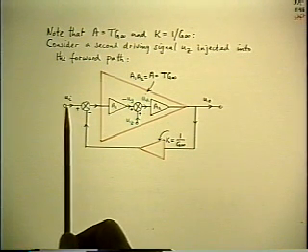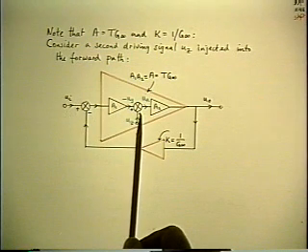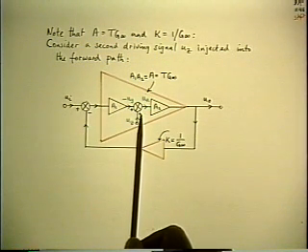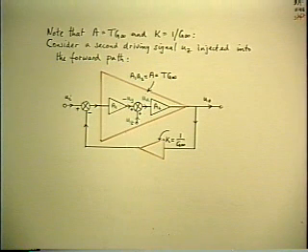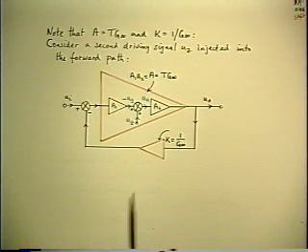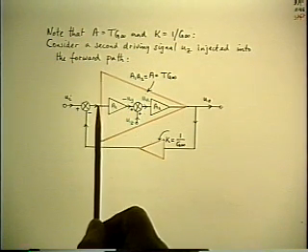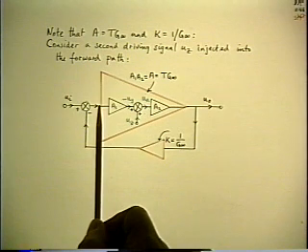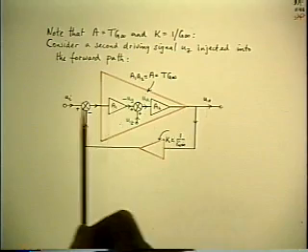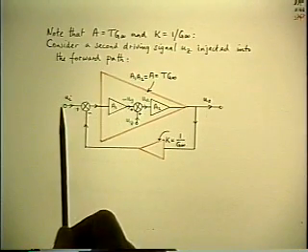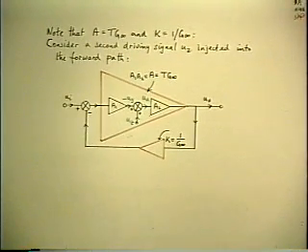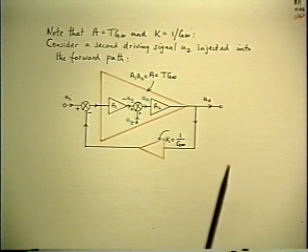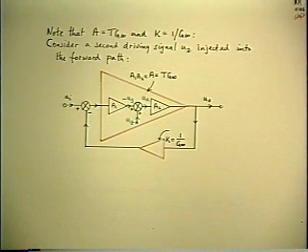Apply the input signal UI and inject the test signal UZ. Two sources. You can choose any other signal in the system you like and null it. That's always possible. So adjust them until you null the error signal. What happens? If the error signal is nulled, the output divided by the input is G infinity, because that's the definition of G infinity: the ratio of output to input when the error signal is vanishingly small.